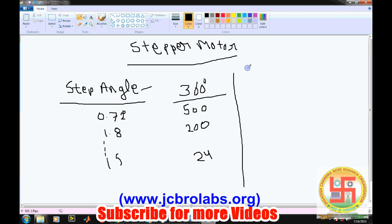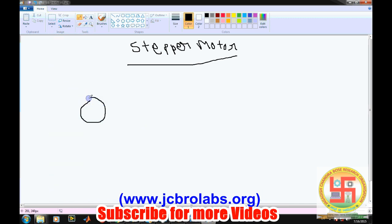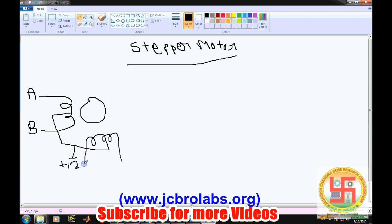When we say we have applied a single step, that means we talk about the voltages which have been applied to the windings. In our case we will be interfacing a unipolar stepper motor. So let's first have a diagram of the stepper motor and the pins we are concerned with. These two pins are common, which will be connected to plus 5 or plus 12 volt, and this is A, this is B, this is C, and this is D. Applying a step means the combination of ones and zeros applied to these windings.